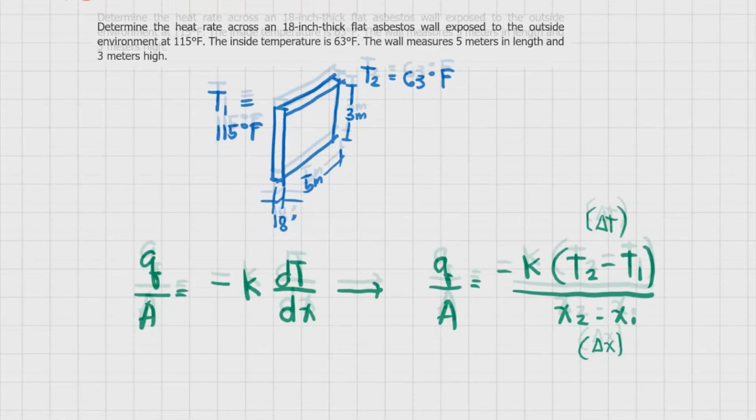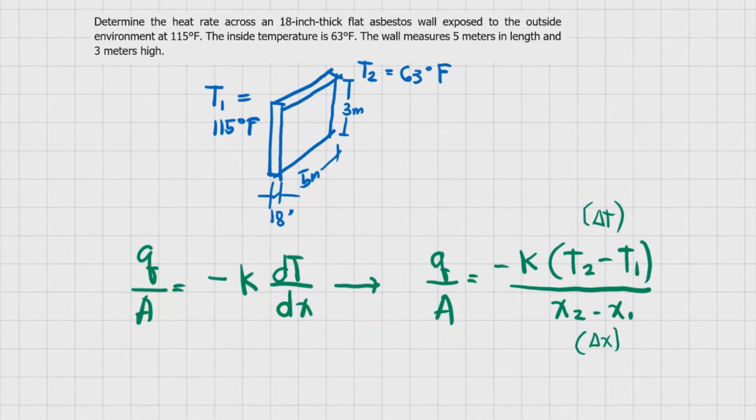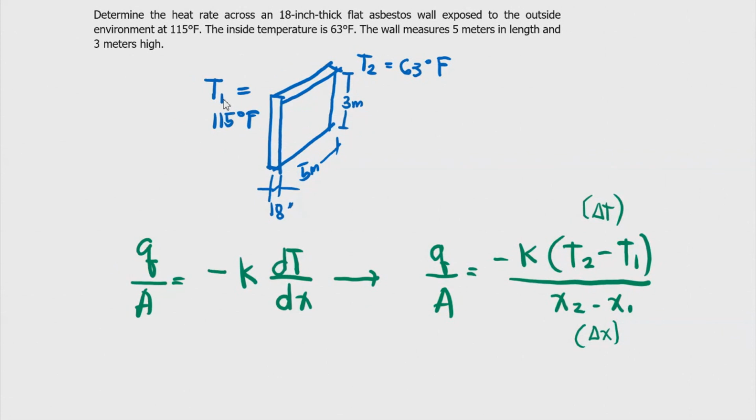So, if, for example, yung ating thermal conductivity has, of course, meron tayong side 1 dito and then side 2, it has a temperature gradient. So therefore, I need to evaluate yung thermal conductivity dun sa gitna ng temperature na to. But if ever meron tayong mismong equation or function in terms of T for our thermal conductivity, then we will substitute this equation to that expression na given yung ating K. But for now, since wala naman tayong ganong equation, then we need to use a table in the Perry's handbook.